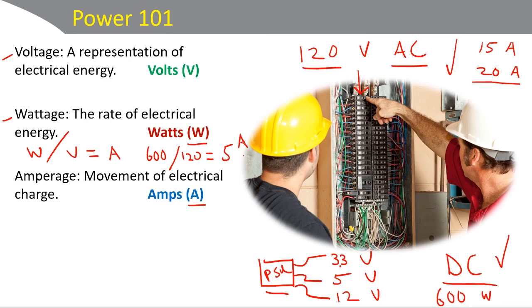So we want 5 amps for a particular computer that's going to be running. Now, it could be less than that. You might not draw all that power at the same time. It depends on what's inside the computer and so on. But effectively, we could then say, okay, we can have 4 computers on a 20 amp circuit. Now, of course, you have to add monitors and things like that, but they use a lot less power than the computer itself and that PSU, that's 600 watts. But generally, you could do about 3 or 4 computers on a 20 amp circuit.